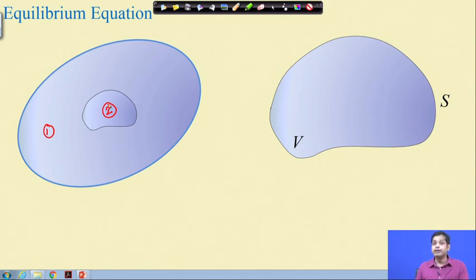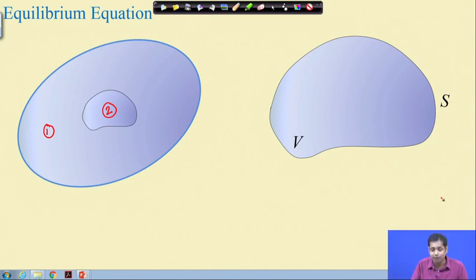If you recall, when we discussed traction, we defined traction as a field through which these two different parts interact with each other. So, if we take this part out from this object, then we will have traction on these surfaces. And through this traction, this small part, part 2, will interact with part 1.